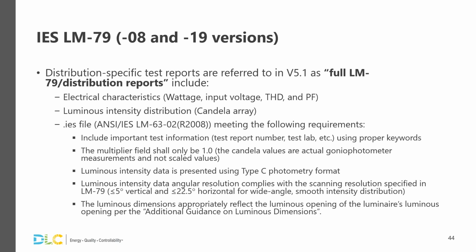However, these are not new elements within the IES files, but mostly the information that is often omitted or incorrect in the IES file submission. So our goal there was to really clarify and be very detailed about what's required there. Again, there's more in the document, especially some additional guidance on luminous dimensions for different fixture types, which is important for calculating the luminaire's UGR values.